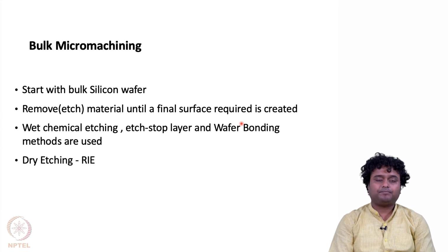Then there are some bulk dry etching techniques also. Other than using only liquids or liquid chemicals, we can use gases also for etching away the material. These are called dry etching techniques, and RIE, or reactive ion etching, is one of the very popular techniques for dry etching.